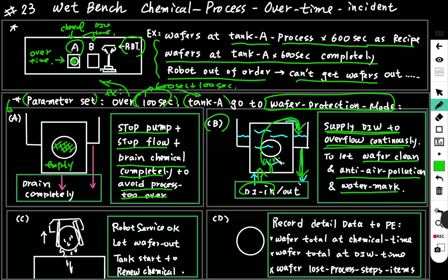It will leave a watermark, even a chemical mark. It can hurt the wafer. Sometimes we cannot let the wafer be reworked. So keep supplying the DI water to clean the wafer and let the wafer sink in the DI water to protect it.